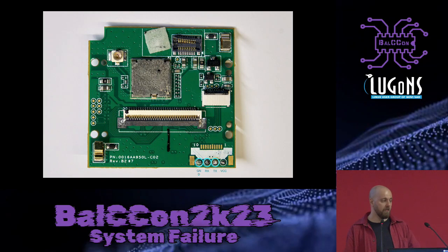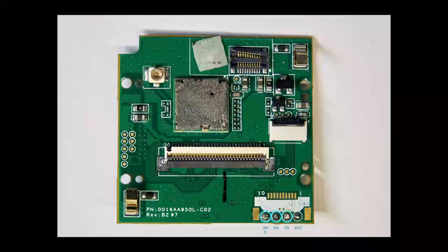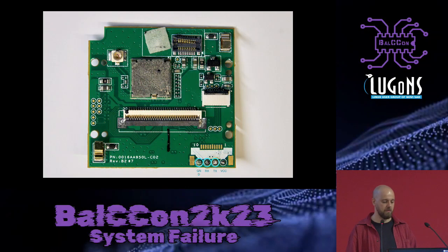After disassembling the device to figure out how it works, how it's built up, you can very easily spot serial access on the device, but it's relatively useless because the bootloader is locked. There's nothing running on it. So even though you have serial easily accessible, you don't get much.